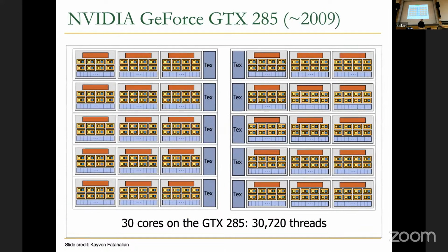And the number of SMs here, for example, the number of cores in this architecture is 30, but today GPUs mostly have more than 100 cores in their die. So you can see the total number of threads that we have. Imagine that we have 100 cores and each core can run 2K threads. So in the end, you will have 200K threads. And the register file is also 256 kilobytes per SM. And you have more than 100 SMs, so you can see how large the register file is for such systems.